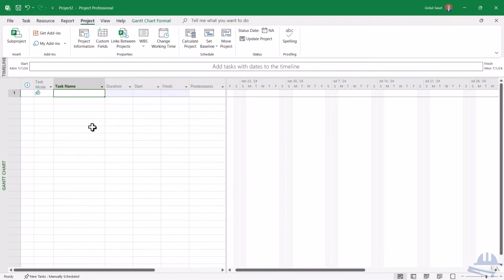And for all these tasks, you have to know every detail. Okay, like for example, when you do the excavation, how you will start the stone soiling works. Let's say that when you start the excavation, there is a whole lot of the big plot that you are excavating, and one edge of the excavation you have already made. So you have to think whether you will finish the excavation completely and start the stone soiling work, or you can start the stone soiling work once you have excavated a sufficient amount of the land.